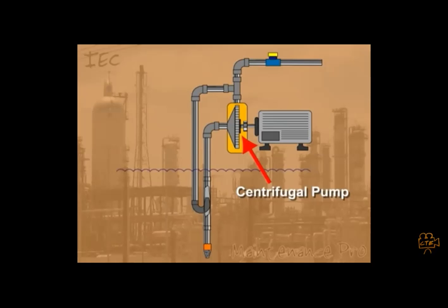The drawback is that you need a greater amount of energy. Your electrical energy will be more, so if you are using a jet pump, the electric bill will be more. It will consume more energy because you are getting only some amount of water at the outlet. Every time some recirculation is going, and at the outlet you are getting some amount of water. Why are we doing this? Just to remove our limitation of 10.2 meter. So you can write this.